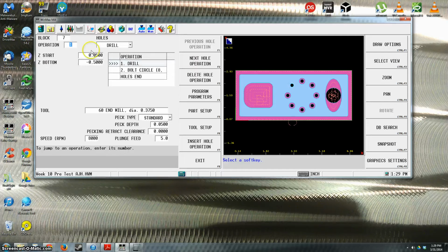As far as stuff like this goes, I'd never just plunge an end mill to create a counter bore hole, unless I absolutely had to. You get a really bad finish usually, and your hole is basically whatever your end mill size is. So if your end mill's really undersized or tapered or chipped, it wouldn't be exactly the size you want it to be. If you take a smaller end mill and actually bore this out, you'll have a much better finish, and the hole should be exactly the size you want. It's just a counter bore, so it's not too critical.